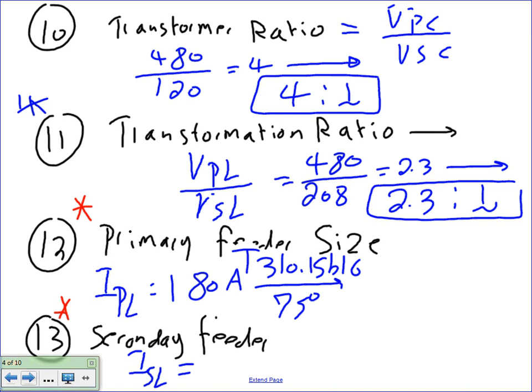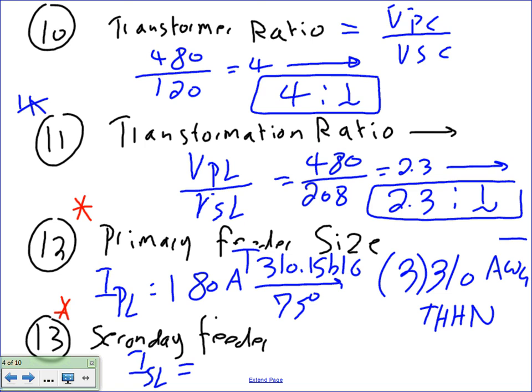What's the conductor and how many conductors do I need for this system? If you go there, you need 3 aught, and how many conductors? 3 of them. Why 3? AWG, and what insulation do you need? Let's say it's inside. We're going to use THHN. That's it.